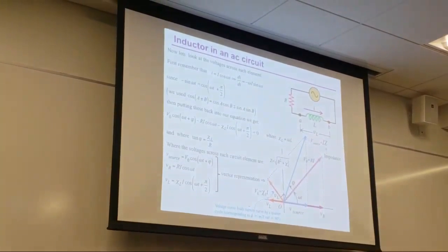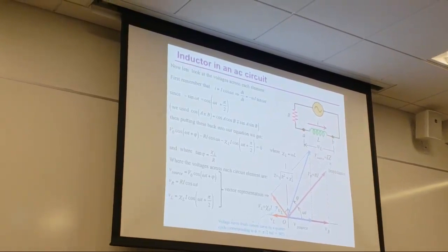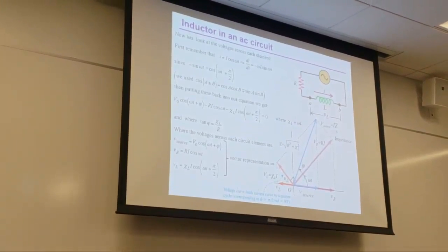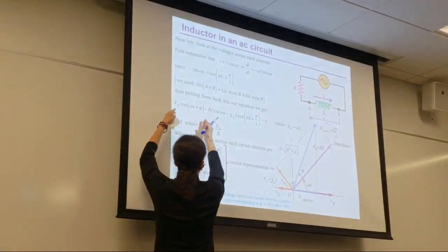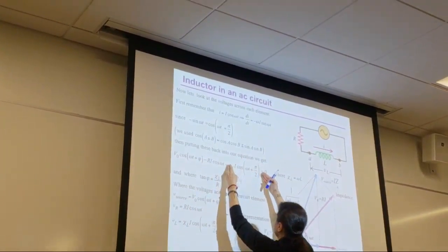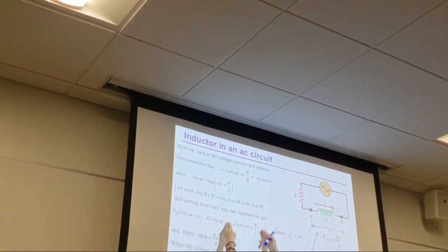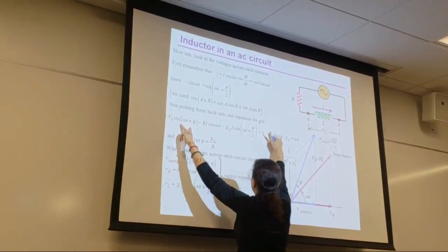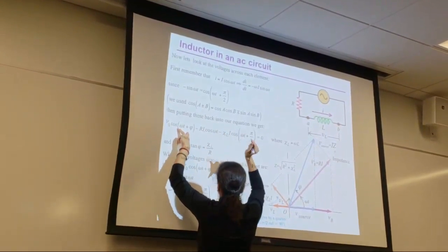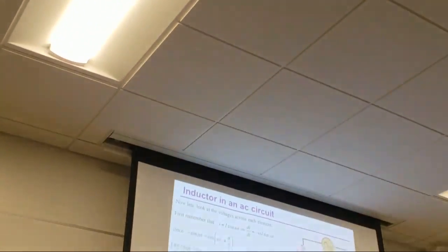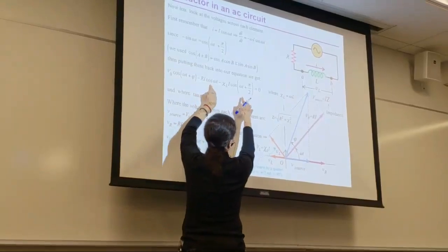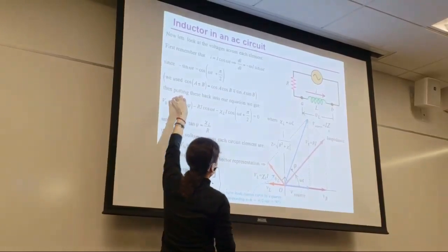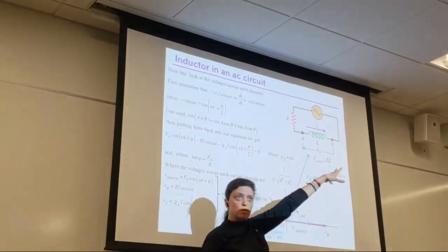And therefore the voltage across the source has to be equal to the sum, right? So the equation, where is it? Yes, here. This is the voltage across the source, the voltage across the resistor, the voltage across the inductor. All right? So if I put them on this side of the equal sign, the voltage across the source must be equal to the sum of the voltage across the resistor plus the voltage across the inductor. Yes? If I just rearrange these equations so we can read them that way.